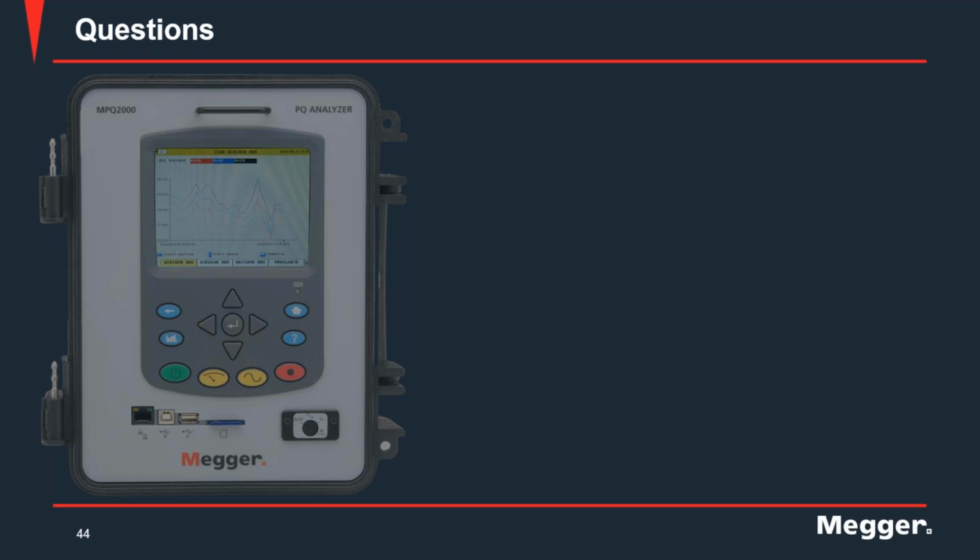So there is still a lot of work to be done in this range, but again, the limiting factor is the CTs and PTs and the equipment. So whatever you're trying to do, harmonic monitoring of high voltage, you're going to need to determine how high a frequency you want to measure up to and verify that the PTs and CTs have the required bandwidth and the equipment you're using has it as well.